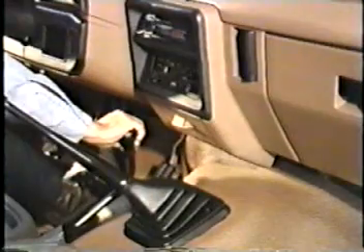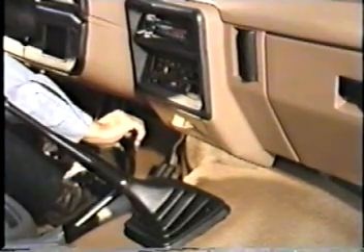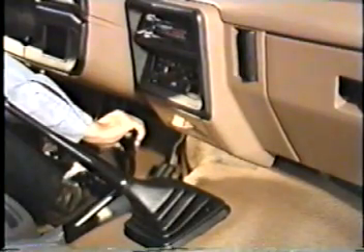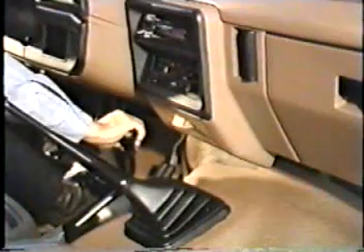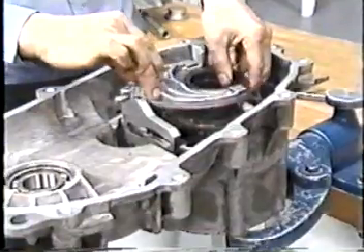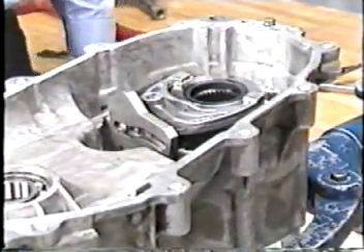With one insert missing, the uneven pressure on the reduction hub makes it extremely difficult to shift. When it did go into gear, the missing insert prevented complete engagement, resulting in jump out during deceleration. Not being fully engaged in either gear caused the grinding. After replacing the high-low fork, inspect all remaining components before reassembly.